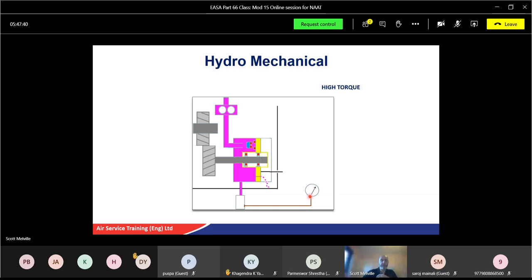So gears rotate, they move a piston inside the cylinder. As shown in the image, power increases, oil pressure created within the cylinder increases, and that pressure is transmitted to the gauge. The bleed hole within each cylinder allows the piston to reach a sensitive position as the torque reaches a point where it balances the thrust produced by rotation of the shaft. Okay, so again, that'll be linked to the other system. Any over torquing you will obviously have to watch, especially in piston engines, for manifold pressure, but any over torquing will be controlled as well by a governor or maybe a propeller control unit. So it'll be all working together. If you're getting too much torque, then it's either up to the pilot or automatically by the system.